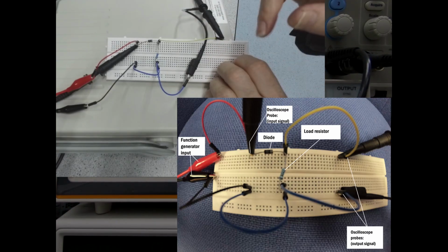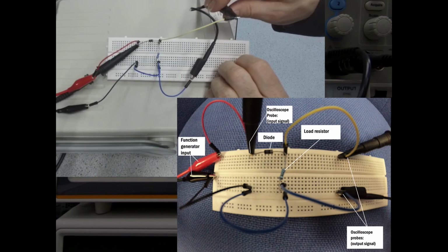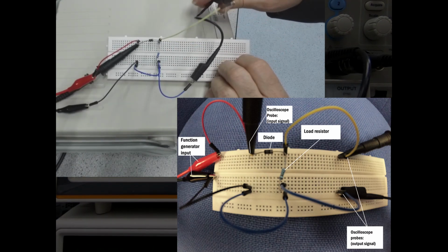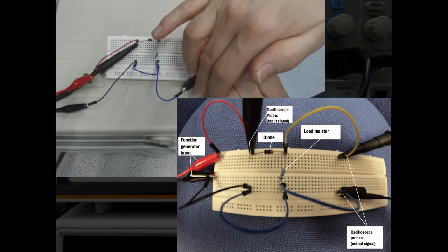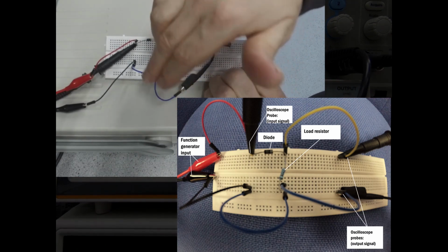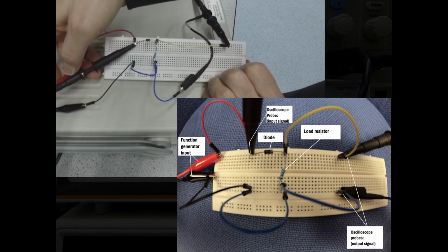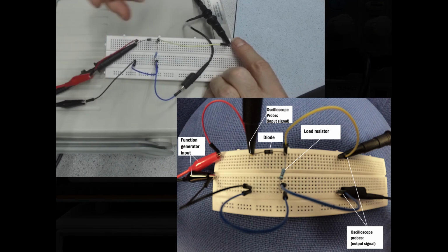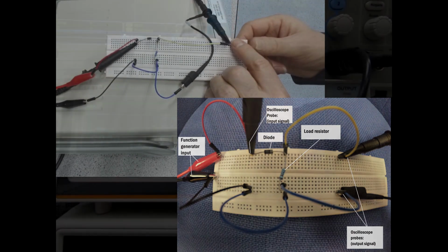Okay, the oscilloscope is connected in two places in this circuit. One straight across the load resistor, so with the main probe on the cathode of the diode, the screen return on the other end of the resistor, common to the black terminal for the function generator, and the other oscilloscope probe is displaying us the input, and that's going to be straight on the anode of the diode, straight from the input from the function generator.